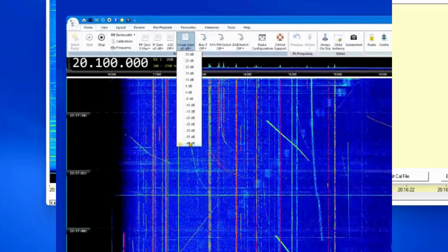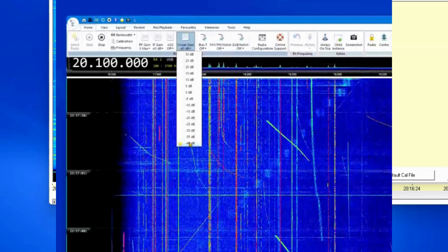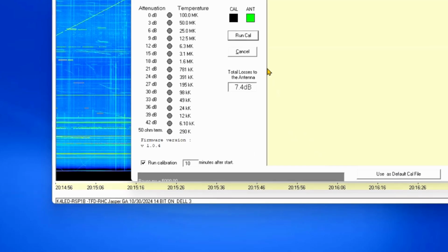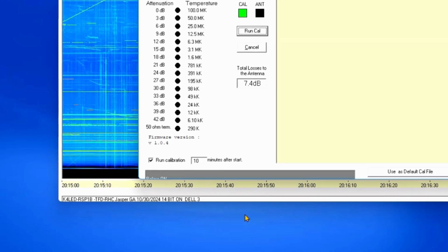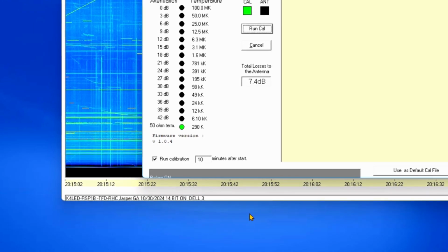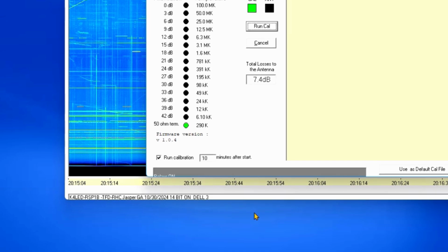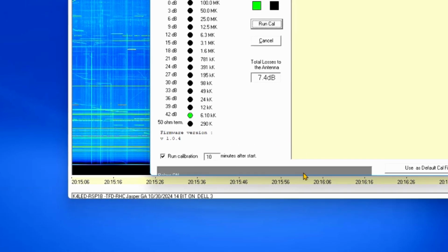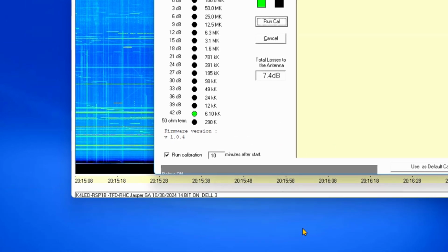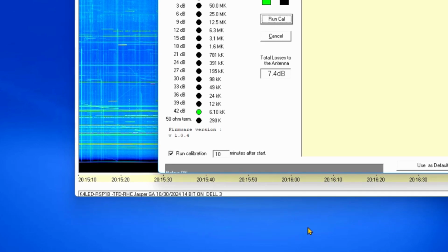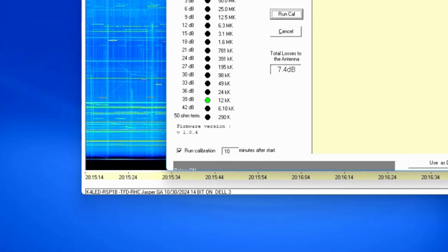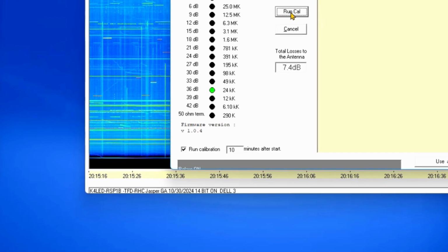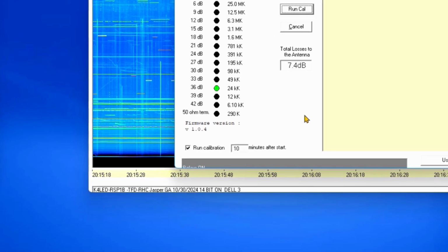First, only concentrate on the bottom left corner. Adjust the two settings, SDR console RF gain and IF gain, to move the bottom left of the plot line into the bottom left corner as close as possible. In RSS, again, click the Calibrate menu, then run Cal. You may need to run the Calibrate menu plot several times to get it as close as possible.